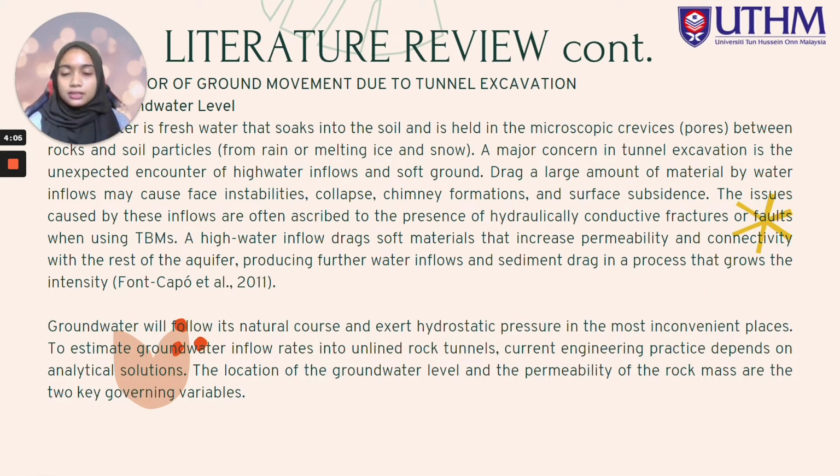Some of the factors that I have included for the ground movement is groundwater level. Groundwater is fresh water that soaks into the soil and is held in pores between rock and soil particles. A major concern in tunnel excavation is unexpected encounter of high inflow in soft ground. Dragging a large amount of material by water inflow may cause face instability, collapse, chimney formation, and surface subsidence.